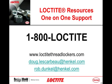The K factor is one of the more misunderstood parts of bolting, in that it's a collection of every variable that changes in a system. But the questioner is correct in that it only applies at assembly. When you put it together and torque it down, how much torque you apply relates to how much clamp load. But once it's together, you're not actually concerned with it anymore.